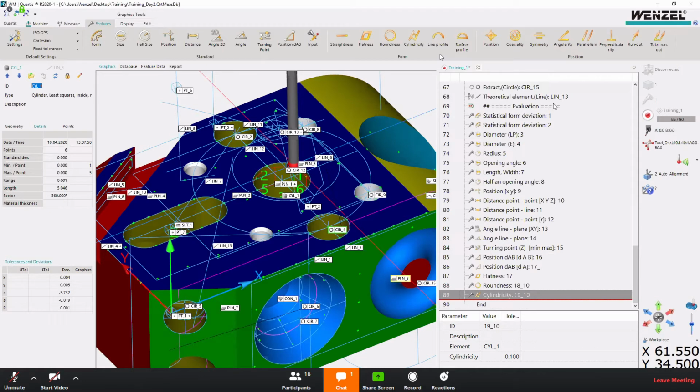So if there is no datum for the line profile and surface profile, then that means it's just controlling the form. And then if there are datums, depending on how many datums it has, like ABC, if it only has an A, then maybe it just cares for the locations. And if it has both, maybe it cares for the form, locations, and orientations, and so on.